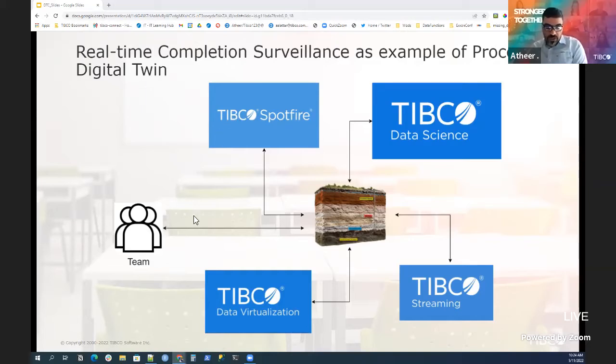This digital twin demo is an example of a process and equipment digital twin, where we monitor different processes, for example, the fracturing activity, pressure trends, any anomalies, the equipment, the pump statuses and other related parameters, and the assets during this process, for example, any fuel consumption, propellant consumption, and any other consumables, like the friction reducer.